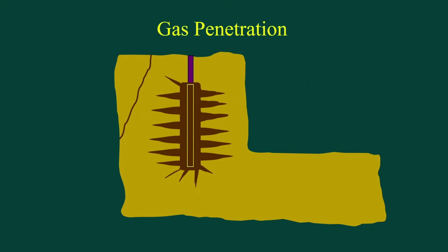Meanwhile, adjacent to our blast hole, those initial fractures are now being invaded by hot expanding gases which the explosive has generated, and that gas penetration opens up those fractures further and further.